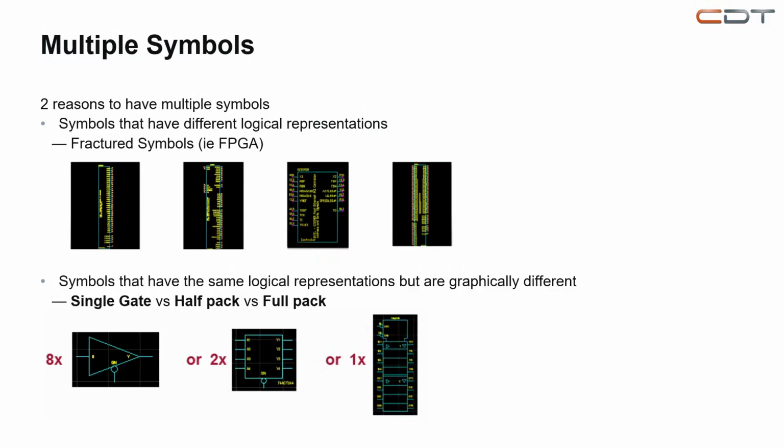And if your component has a lot of doubling pins, like I was showing, it may also be related to the schematic that you're creating, and it will not be nice to have only one full symbol because of huge amount of nets that you need to connect to this symbol. So you can split it into a couple of symbols and put them onto different places of your schematic.